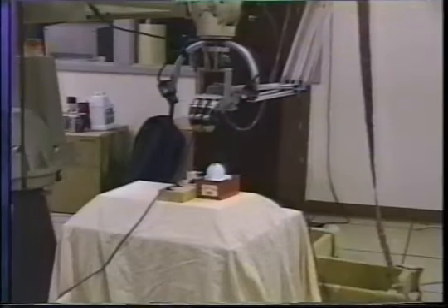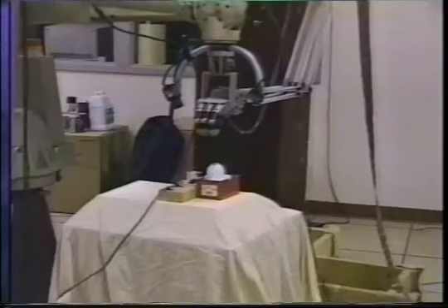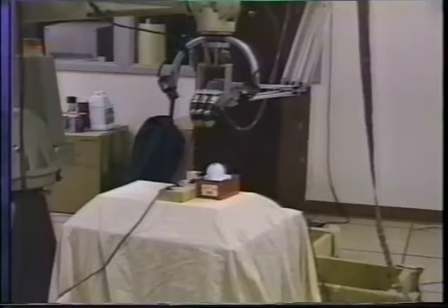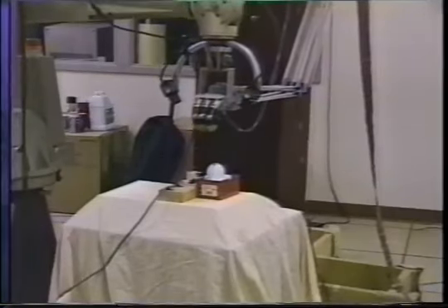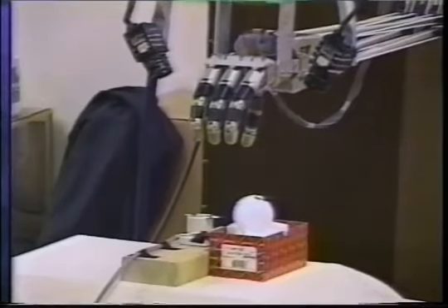In the first task, we use a robot arm and hand to pick up, transport and screw in an ordinary light bulb. 2 cameras are mounted to the left and right of the hand. The robot joint motions are controlled directly from camera space. Special markers on the bulb and socket are tracked in both cameras. The controller goal is to bring the bulb markers to a predefined point between the robot fingers.